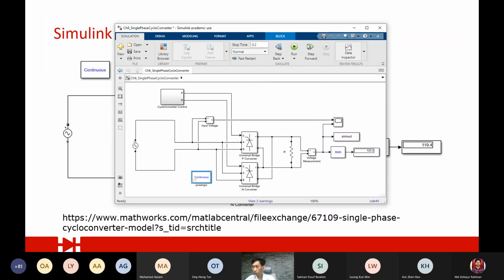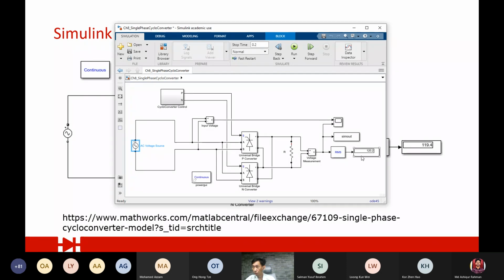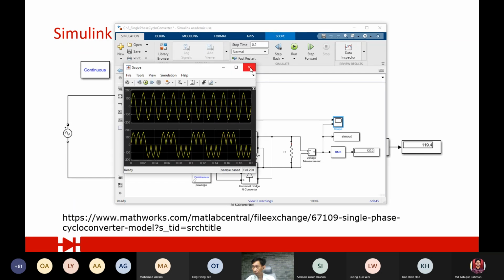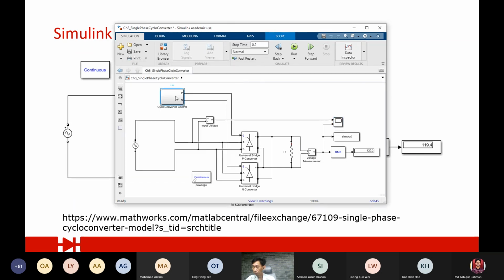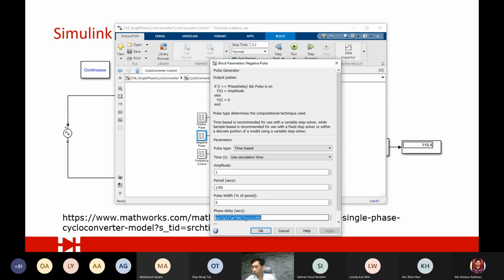All right. So if you want to control the magnitude, now the magnitude is 120, because the AC here has a peak of 170, so the RMS is 120. Correct. And these are the waveforms. Now, if we want to control the magnitude, like I said, I just need to set the firing angle. I just need to reduce the time 0.